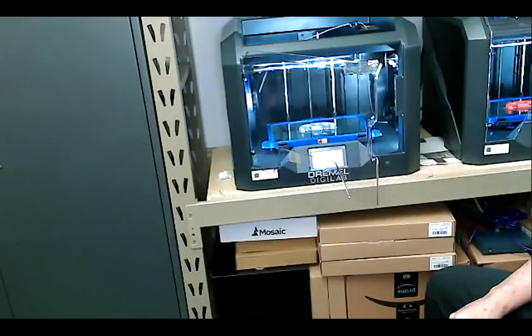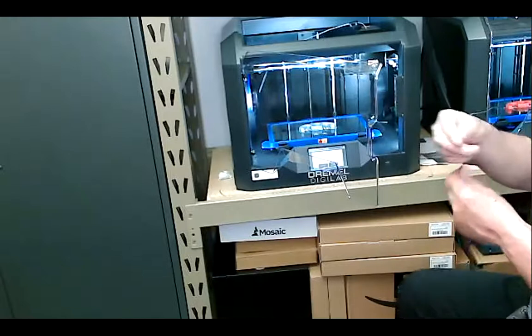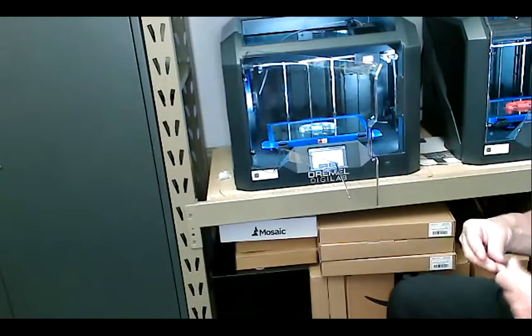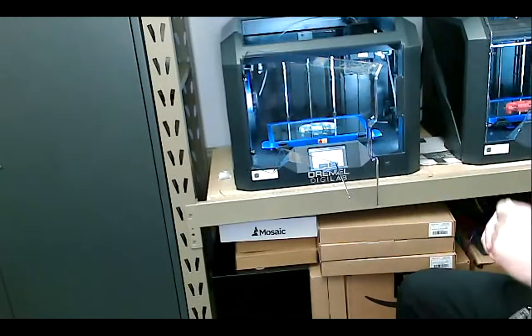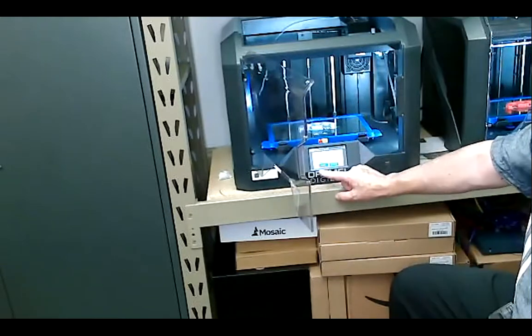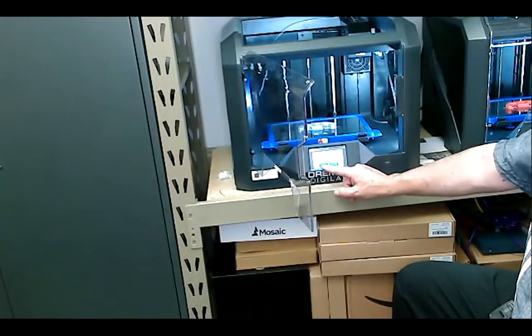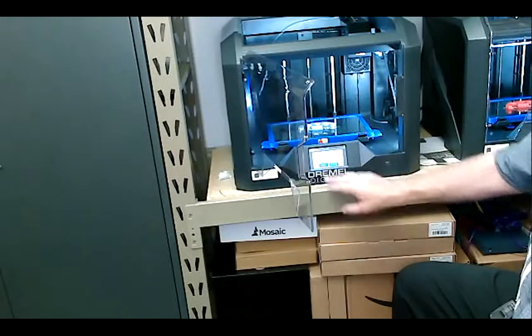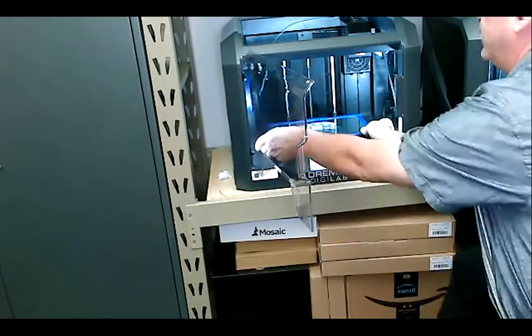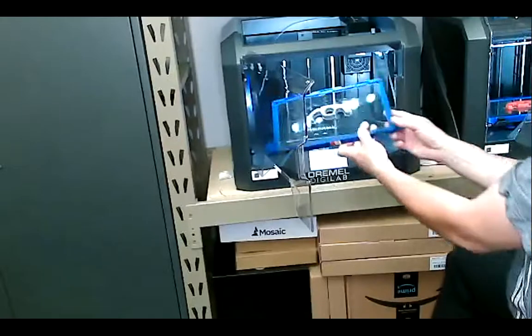I'll accept the material, and then it'll go through and home the machine. You want to have some disposal near your machines because you do get a lot of strings. RFID checks the material and it tells me that we have PLA. PLA is polylactic acid, so I'll accept that. And then I'll take the part off by pushing these 2 buttons down.